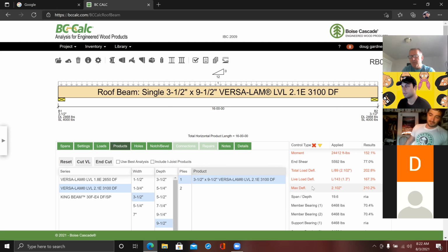And so notice this beam, and by the way, it's just an interesting thing for you to know, but it turns out, and you might be able to picture this, would it be okay for a beam to, you know, when you snowed on it, for it to bend down 2 inches? Does it make sense? Like that could pinch the door. That's a lot. That's bending a lot. Even if it doesn't break, the door doesn't open now, you know, that kind of a thing. And so it turns out that the maximum deflection is actually 1 inch. That's okay. I don't know, that's an arbitrary number, but it's like engineers or home designers said, well, if it's 1, we're okay. If it's more than 1, not okay.